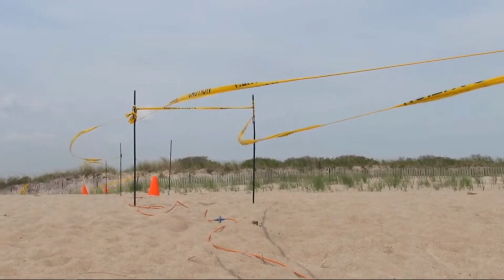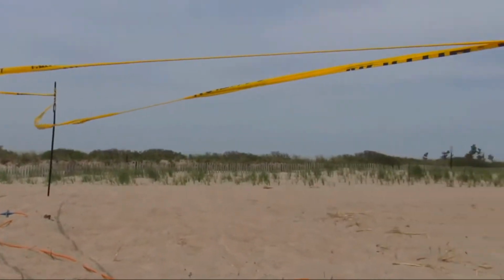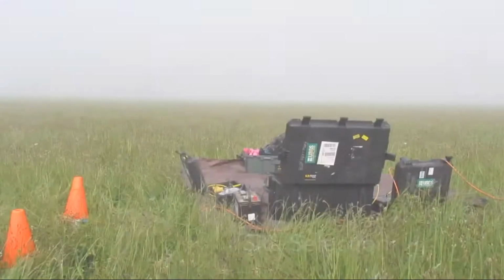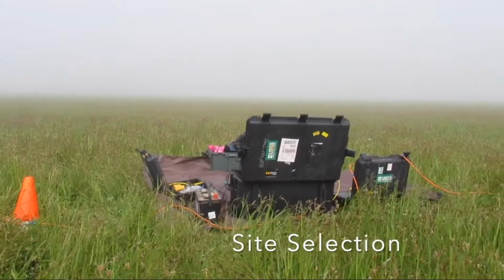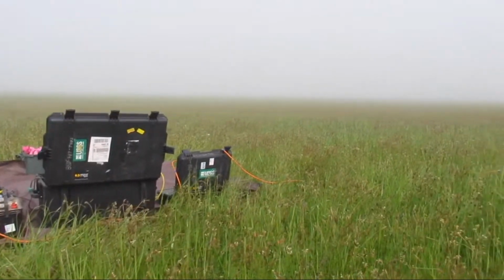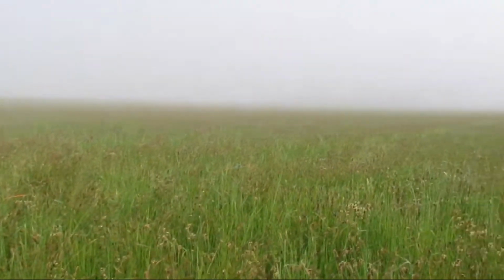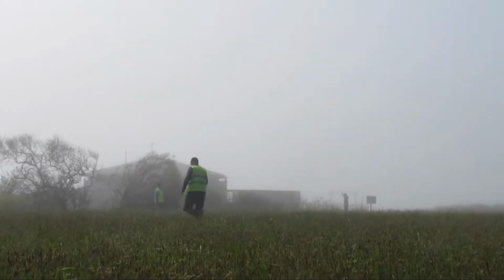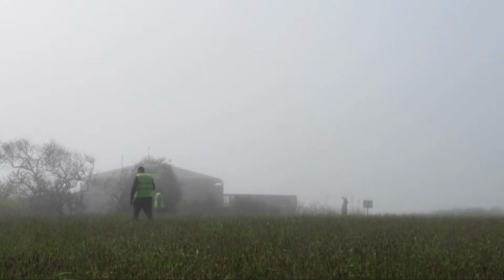In this project, it is mainly used to identify saltwater and freshwater mixing zones underground, which helps us map areas of saltwater intrusion. When choosing a survey site, there's a few things to keep in mind. We have to be away from the roadway, power lines, and not interfere with foot traffic. ERT requires a long extension cord-like cable that should be kept as straight as possible during a survey, so our site needs to cover a large area of uninterrupted space.